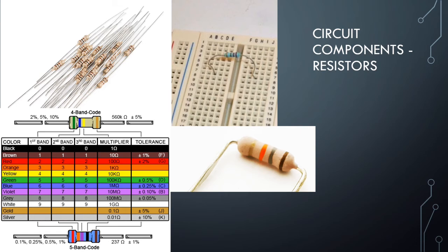That's how we measure the resistance. You might see a resistor that's 1 ohm, 100 ohms, 1000 ohms, 1500 ohms, anything like that. And so it can be difficult to tell these resistors apart, but you might notice that there are different colored bands. Every different value of resistor has a different combination of these bands.